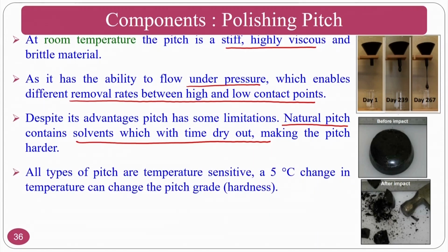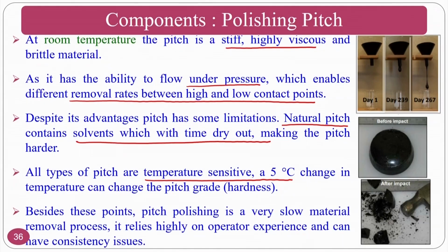All types of pitches are temperature sensitive. That means that a 5 degree change in temperature can change the pitch grade. That means that the hardness, as we have seen in the grinding process, the pitch grade also will change. Besides this, pitch polishing is very slow material removal. That means that the specific energy requirement for pitch polishing will be very high. The material removal is very slow, but the input energy is very high. This is also one of the drawbacks of polishing pitch.